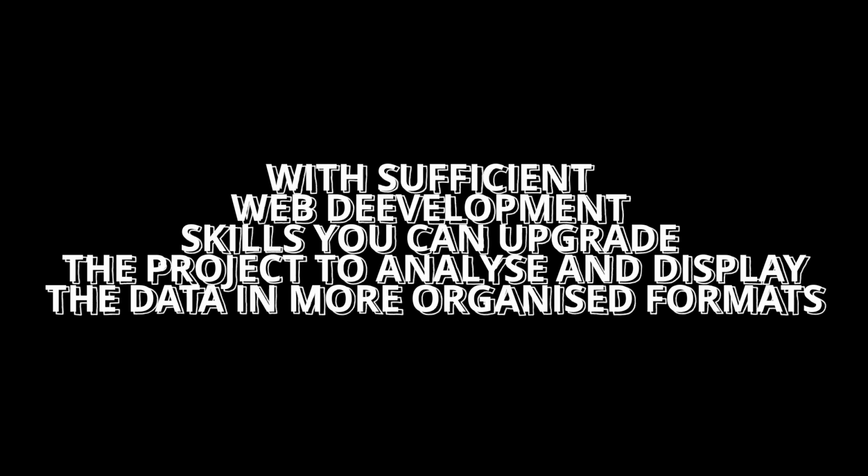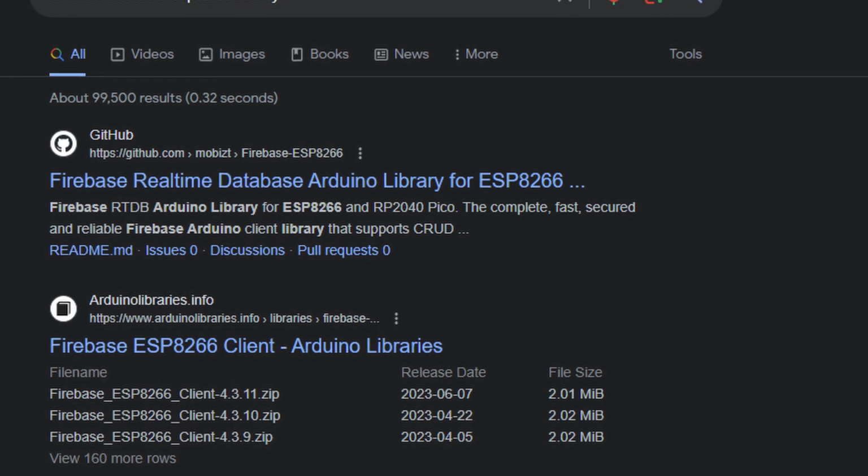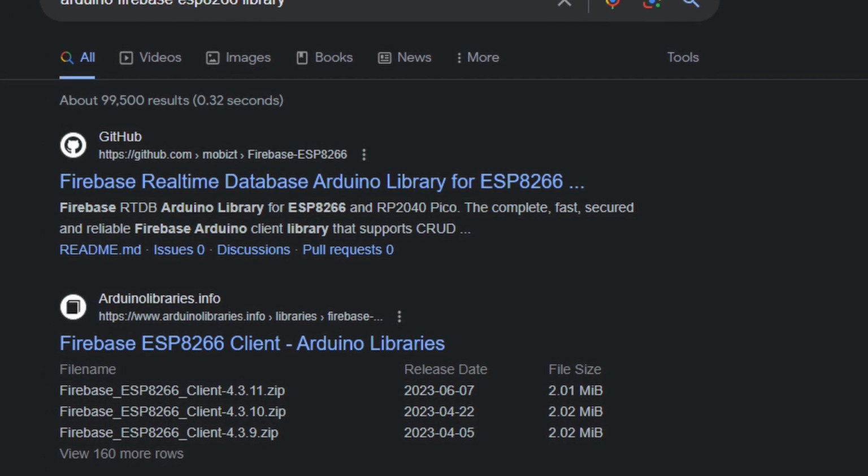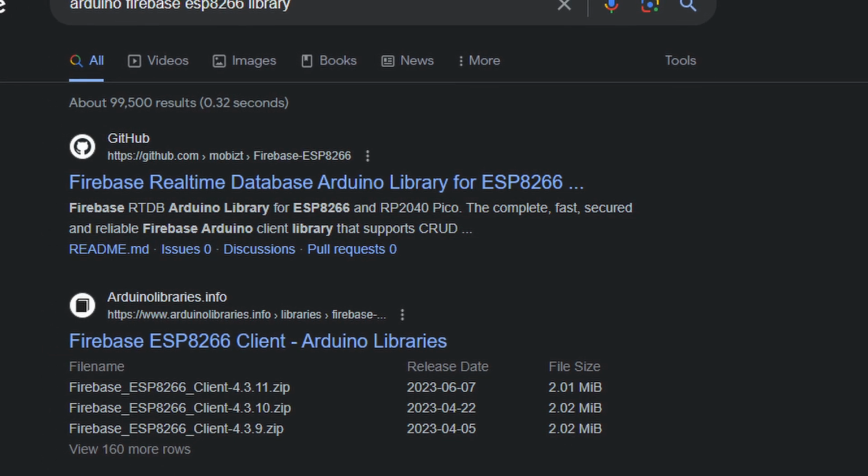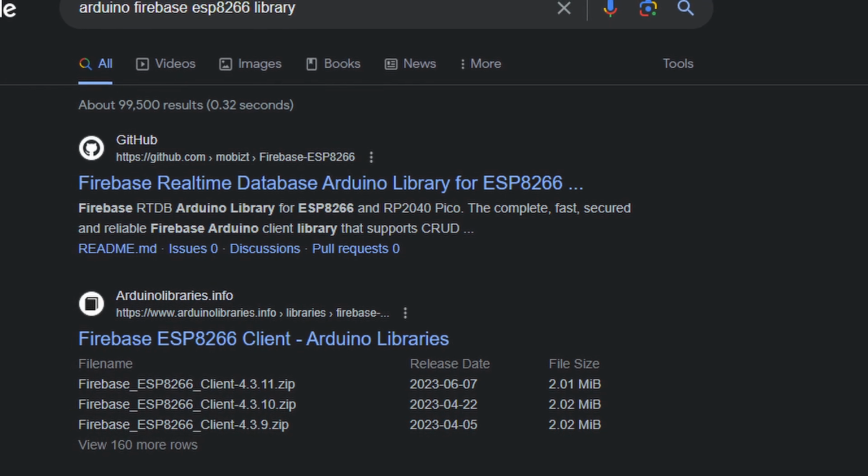So in this case, where you have your card scanned and this unique ID has been taken, now the ESP01 Wi-Fi module, which is based on the ESP8266, is supported on Firebase database, but it has an old library, so you'd have difficulties using it.